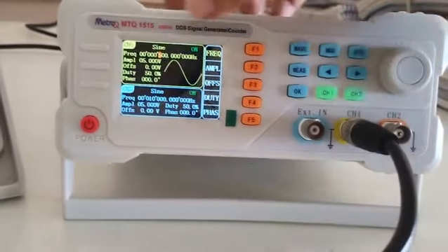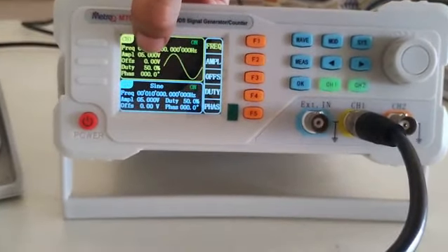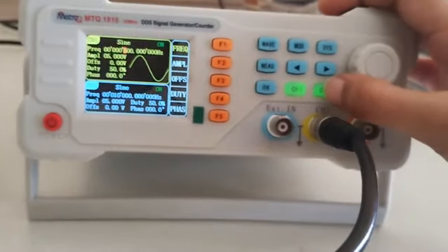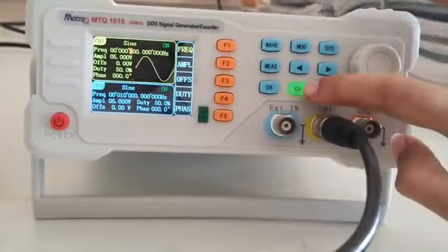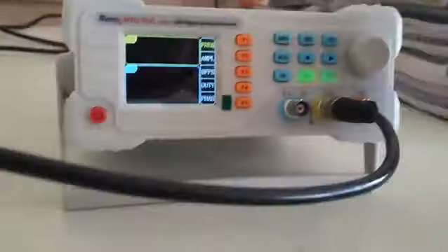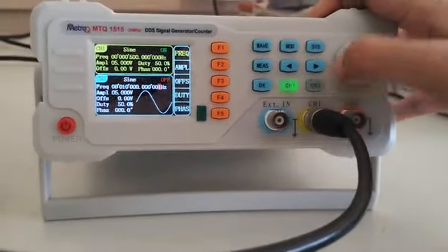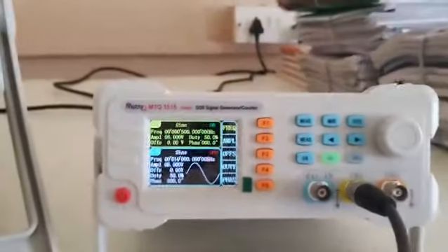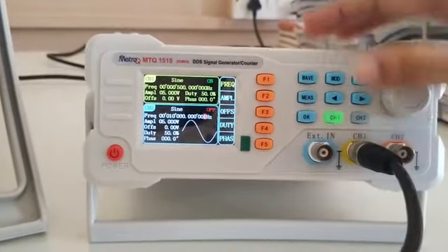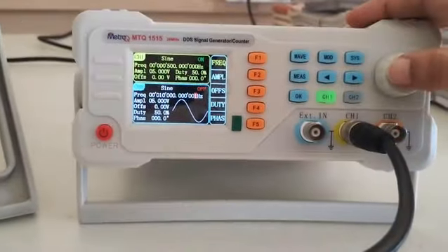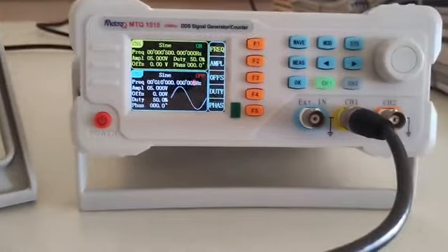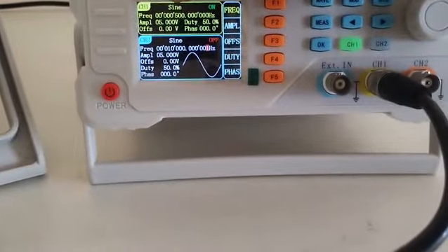Okay, and we set the amplitude on 5 volt and offset on 0.0 volt. So that's it. I am giving input to channel 1, so I will turn off channel 2. So here I applied channel 1. The CRO, that is the sine wave, I am applying.